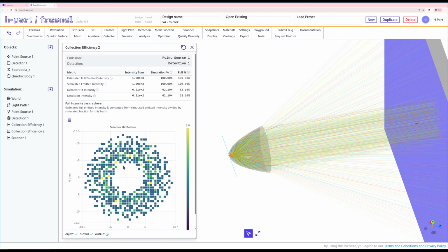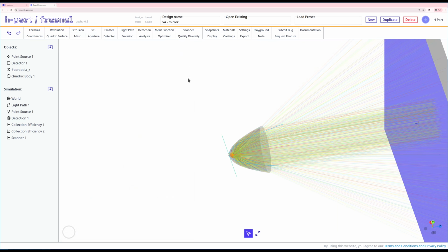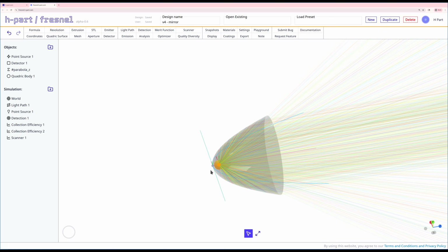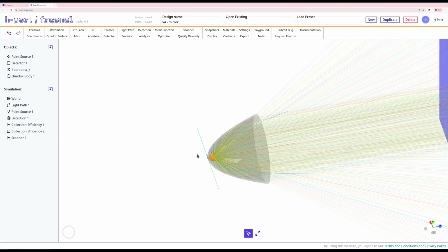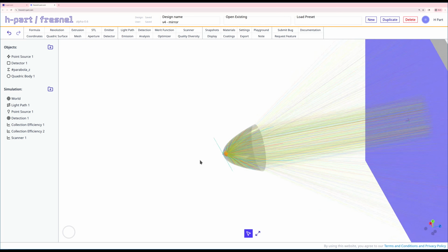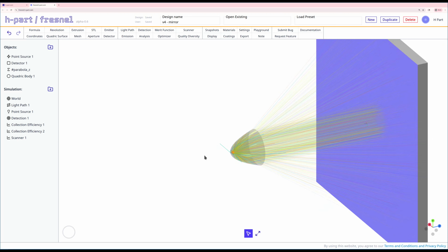We understand why it's a donut. The donut's gotten a little bit narrower because the bottom of our parabola has come closer to our LED. And now the only thing that would be left to consider is whether this is manufacturable, whether maybe we're going to cut off the bottom of this when we mount it onto the PCB where the LED is. These are the kind of questions that we would have to answer. But for now, I'm satisfied with this design.